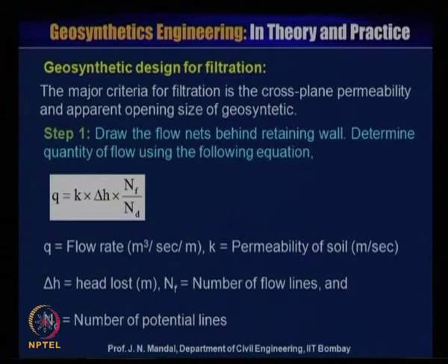Geosynthetics designed for filtration. The major criteria for filtration are the cross plane permeability and the apparent opening size of geosynthetics. So, what are the steps? Step 1, first of all, you draw the flow net behind the retaining wall to determine the quantity of flow